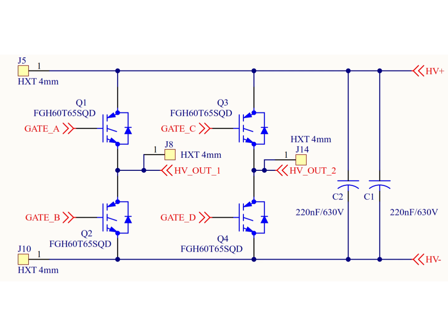Finally, thermal management is addressed by mounting all IGBTs directly onto a heat sink. A thermal pad is placed between each device and the heat sink, providing electrical insulation while maintaining good thermal conductivity. This ensures safe operation, controlled junction temperature, and long-term reliability under continuous high-power operation. This completes the explanation of the inverter power circuit.